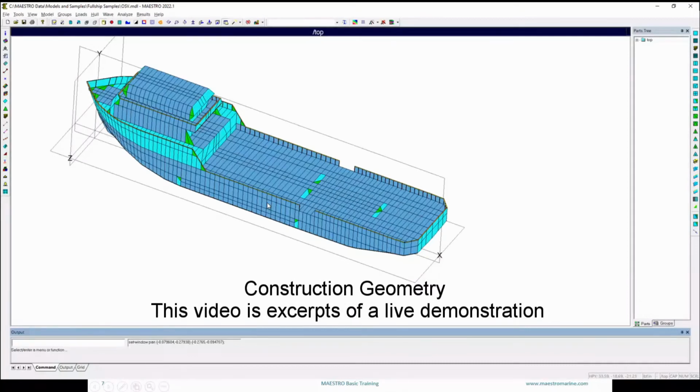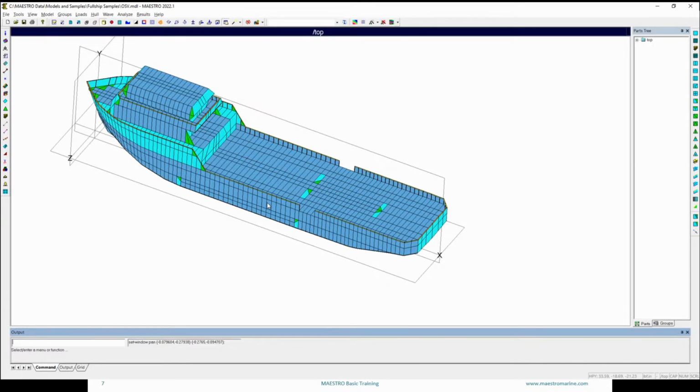the construction geometry in Maestro. Maestro is somewhat limited in terms of reference geometry that can be brought in. It doesn't support having surfaces and things. Like you can't bring in an IGES surface into Maestro. You can import some like polyline 3D DXF geometry.